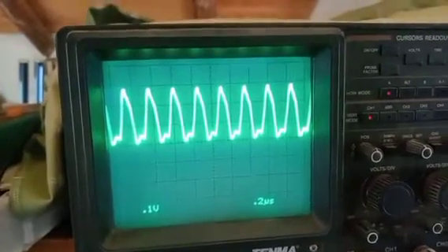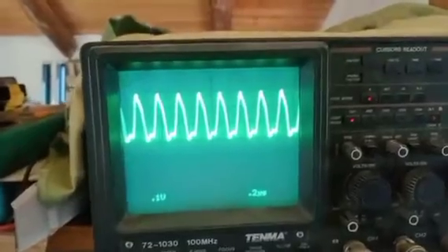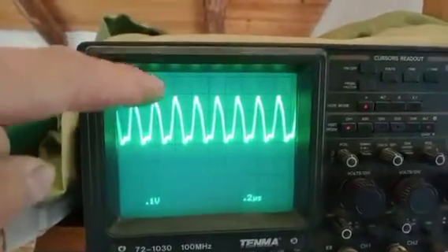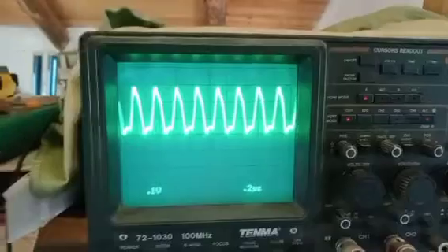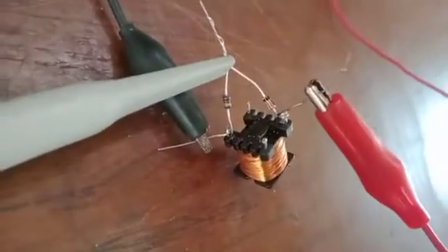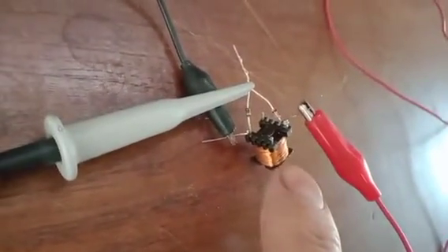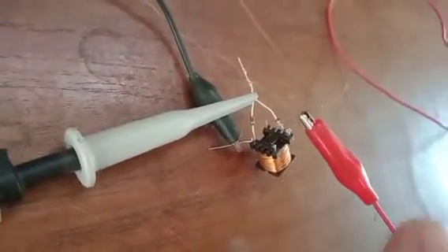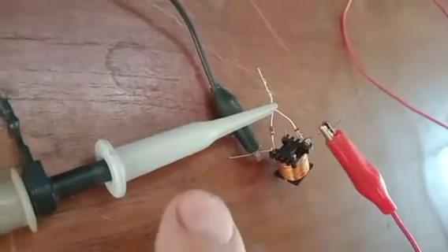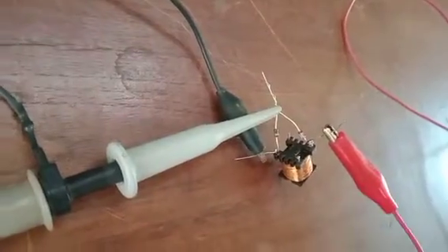This is quite consistent with what we see on the scope. We see there are positive spikes of current, which, according to the polarity of the diode, is logical, as the relatively big inductance will block the pulse in the other direction and let it only flow in this sense.